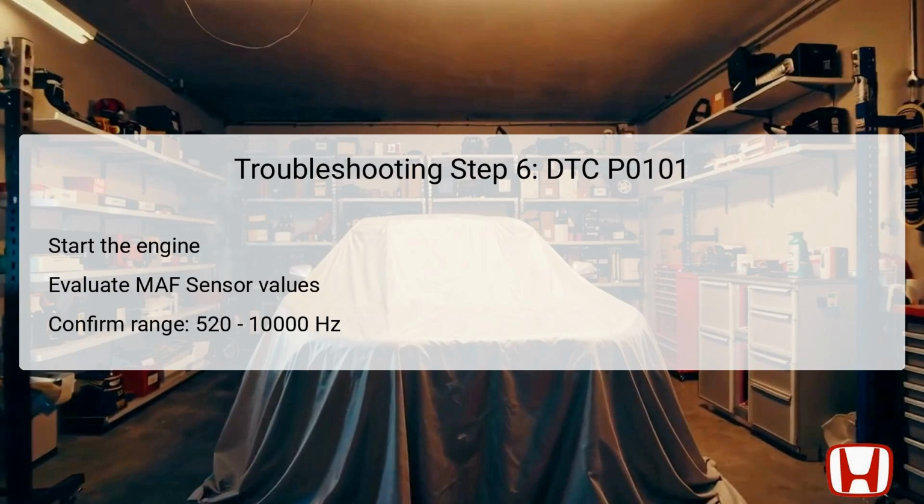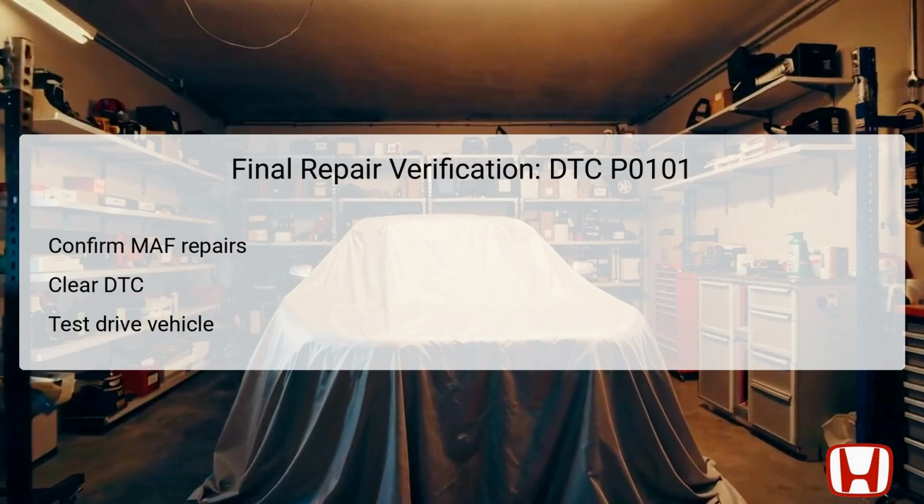After completing all required repairs related to DTC P0101, it is important to verify that the repairs were effective. Start by ensuring that all components pertaining to the MAF sensor and surrounding systems have been corrected or replaced as needed. Following this, it is crucial to clear the DTC using a compatible diagnostic scanner. Once the DTC has been cleared, perform a test drive of the vehicle under various driving conditions to confirm that the issue has been resolved and the MAF sensor operates correctly.